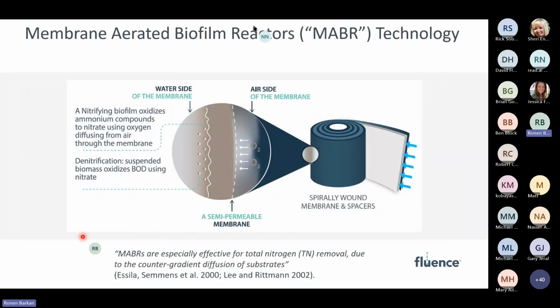Now, beyond just being a very, very efficient diffuser, as you can imagine, this sleeve is a great platform for bacteria to develop on top of it in the form of a biofilm. And unlike MBRs, which MABR resembles by its acronym, this is not a screening membrane. Unlike MBRs, which try to do anything they can to avoid, quote, biofouling, we actually promote the growth of bacteria on top of the membrane, because this is what is going to act as our treatment capacity.